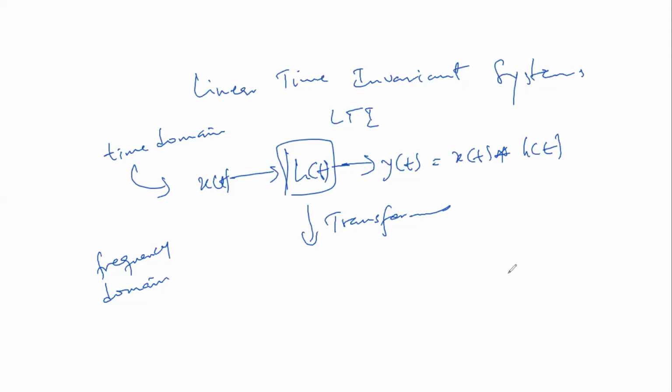Then we also talked about state space models, and from the state space model, having gotten the state space representation in matrix form, we asked what else we can do. We saw that with the state equation, we can tell a whole lot if we are able to pull the system matrix A from the state space representation. With that, we can check if the system is controllable and if it is observable.